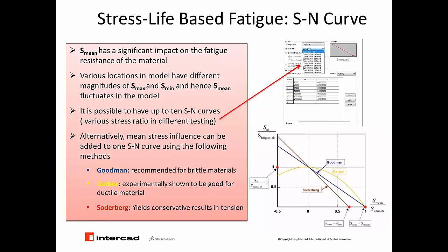As we said, if you have a zero base, it means your mean stress is positive. You're just having a tensile load on your structure. Well, that could be a different life if your load is fully reversed, or your mean stress is zero. You have plus and minus, or tensile and compressive. That is two different life stories.